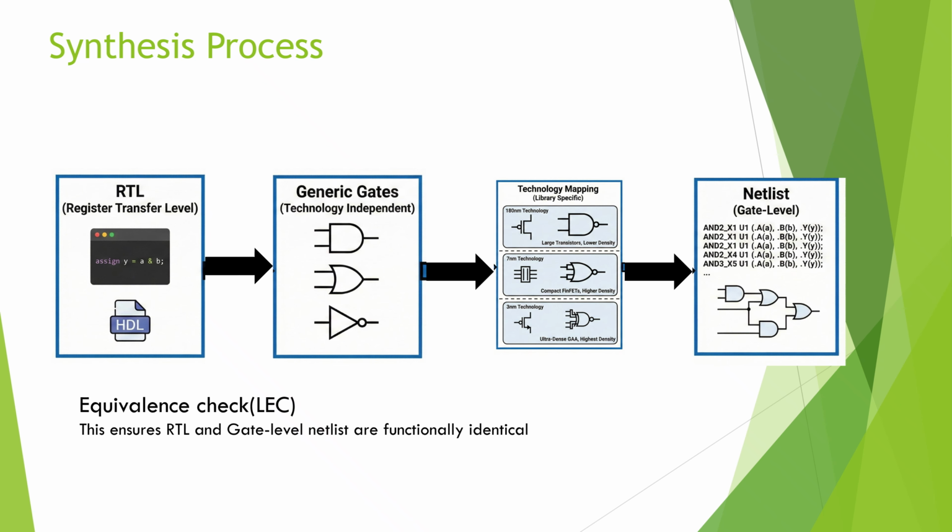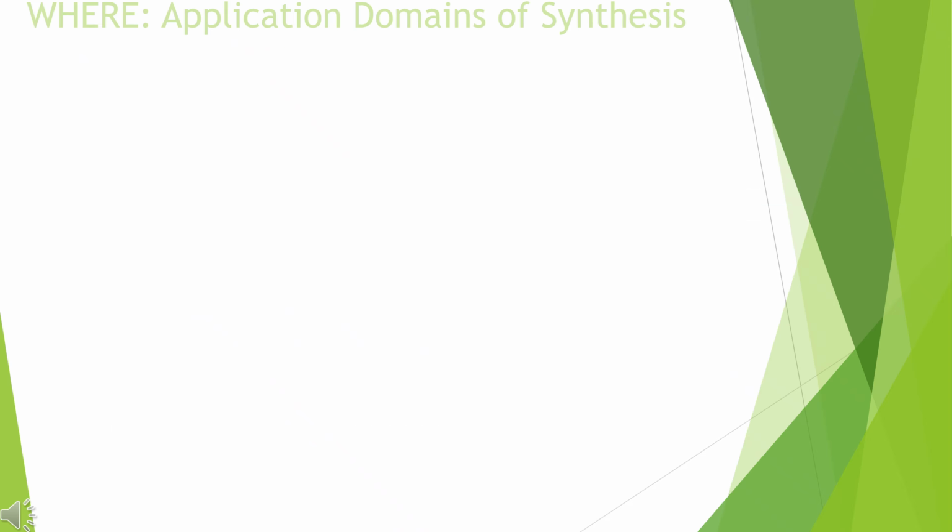So if LEC fails, we know something went wrong. Maybe constraints were wrong or some bug got introduced. We fix that before going to physical design. Exactly. Skipping LEC is extremely risky in any serious chip project.